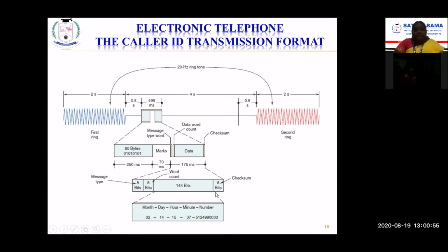And finally, always any data packet that is sent will have a checksum. You might not be familiar with this terminology, checksum. That is what we use in the case of data communication to find whether any errors have occurred. In this machine interaction, it is just going to send zeros and ones as the data information. It will not know whether it is receiving correct information or wrong information. So that has to be checked. For that, we send a following 8 bits of checksum, called the cyclic redundancy checksum.